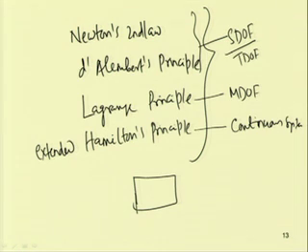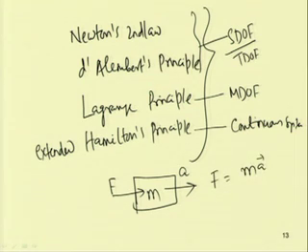After drawing the free body diagram, we separate the whole assembly, and then we write the force equilibrium equation. For example, we write the external force is equal to mass into acceleration, if this external force F is acting on the system and it is accelerated with acceleration a. So, we are writing the equation of motion in this form.